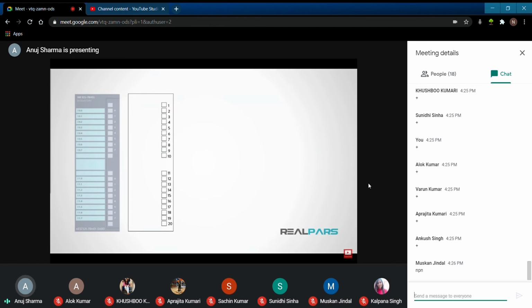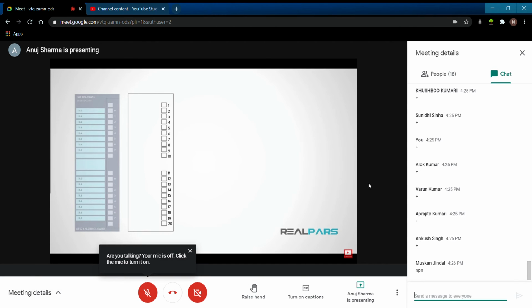The SM321-7BH01 has 20 screw terminals to which the digital inputs are connected. As we saw previously, for 3-wire discrete DC sensors, each digital input channel requires the connection of 3 wires. The SM321 card is constructed so as to accept only PNP type sensors in a 3-wire configuration. Use of NPN sensors would require a different model of I/O card.